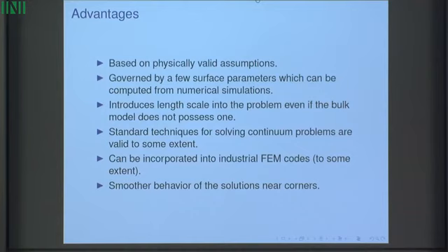An interesting thing about this theory is that introduction of surface energy introduces a length scale into your problems. Suddenly your problems with linear elasticity, which is scale independent, become size dependent. That is an interesting result. Since the bulk theory is the same, linear elasticity, standard techniques are somewhat valid for solving these problems, and hence complex analysis, one of the main tools of two-dimensional linear elasticity, still works to some degree in this area, hence my talk.